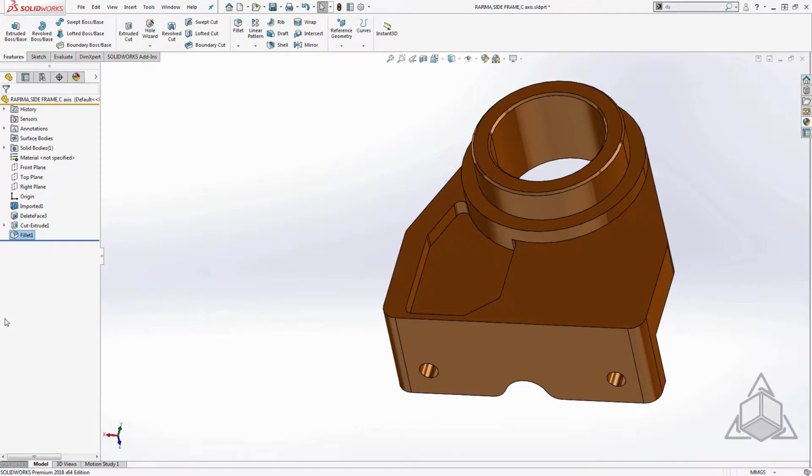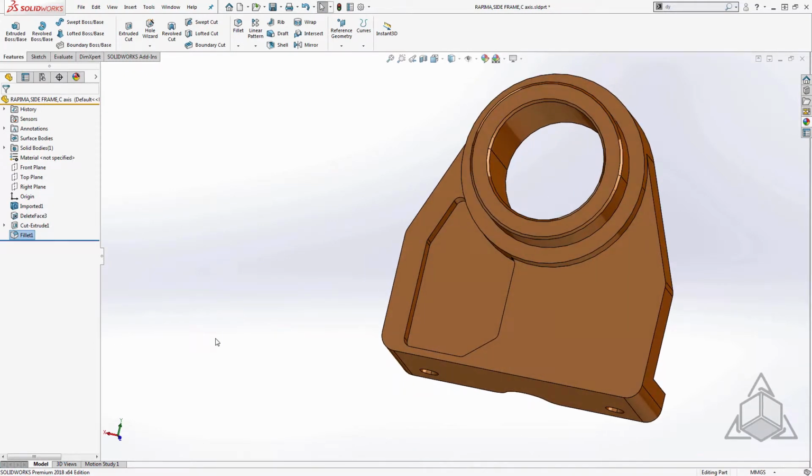and accept the command. At this point, we'd like to mirror the geometry, and here's a scenario that can become a little bit problematic. Oftentimes when we have pockets, we have overlapping fillets and things like that that are a little bit difficult to select from the graphics area. Normally I like to select them from the tree. However, once we've launched the mirror tool, it can be a little difficult to navigate the tree once it's in the graphics area. So in order to pre-select the tools, I actually like to box select directly within the tree.